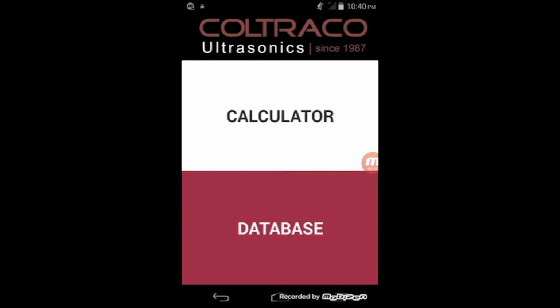The PORTASTEELE Calculator is used as a supporting device for our Portalevel range. So once you've non-invasively taken an accurate liquid level measurement with the Portalevel Max or any other product in our Portalevel range, you can then use the PORTASTEELE to calculate the agent mass. Now this is very important because most regulations state that you need to identify the agent mass using a listed device.